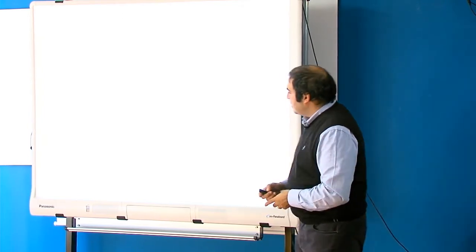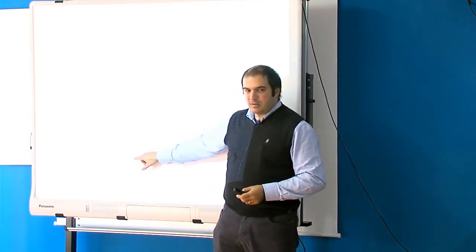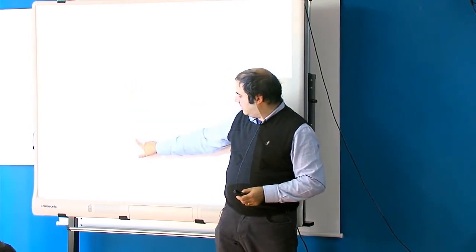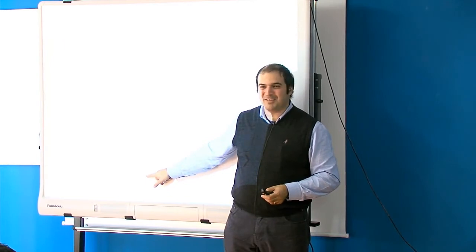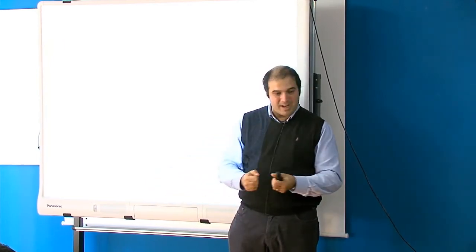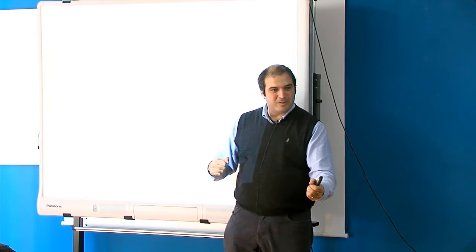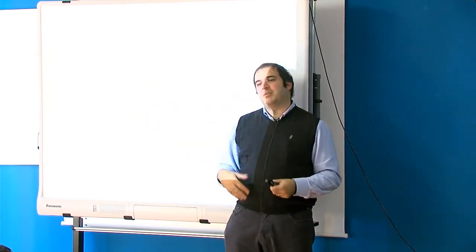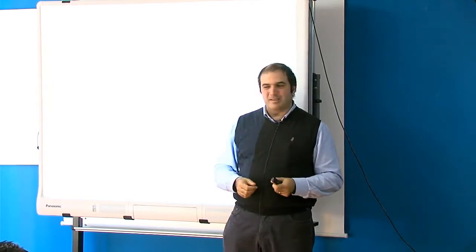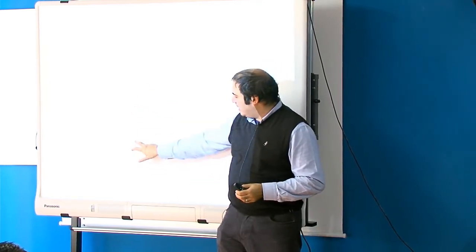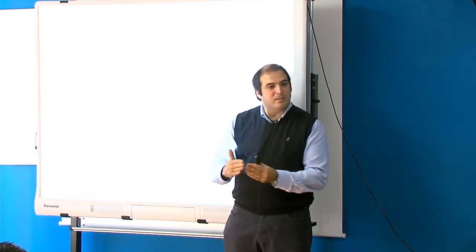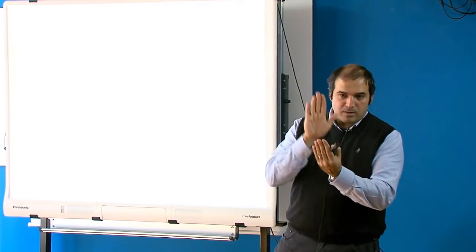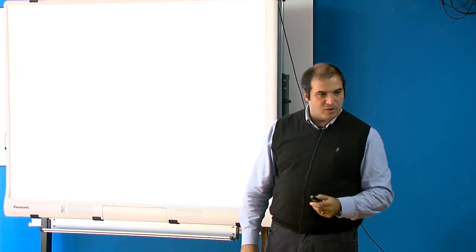The problem is this: if they fall here, when I measure this tone, it has contributions from all these tones, so I cannot separate the information, you see? They are all falling on top of each other. So I can have strong algorithm schemes to do this, but it's not easy to separate these different components or these different mixing products, because they are all on top of each other in this sense.